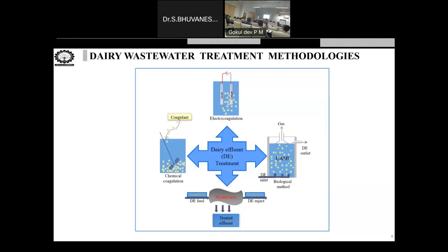But when you want to use it for industrial application, batch operation will be done only for half an hour or 1 hour. That time no issues, you can take some feed, you can take some emulsion, and have stirring so that whatever component we want to remove from the feed will get attached to this liquid emulsion membrane. All these things can happen within half an hour because the emulsion is stable for some time. But when we use it for industrial, continuous application, what happens? This emulsion will degrade, and two distinct layers will form within half an hour. Then how can we use it for industrial or continuous purposes?